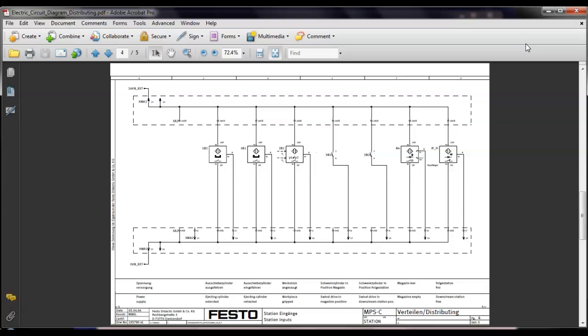The biggest problem with relay outputs is they're electromechanical devices, which means they can do what? They can fail two different ways. And another thing is how fast they can switch. Normally, probably 99.9% of the time, it's fine. But when we get into things like pulse width modulation to control the speeds of motors, these guys right here just can't. There's no way in the world they can keep up with that. That's where you'd have to make sure you had a solid state output.